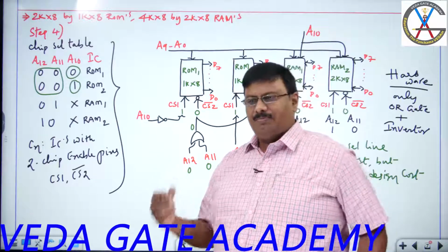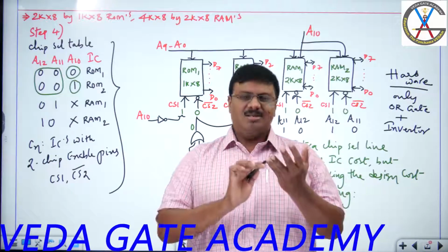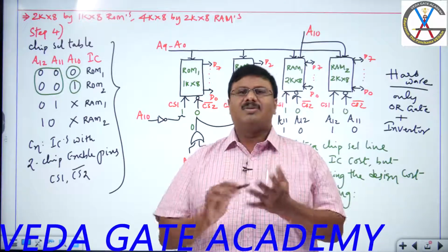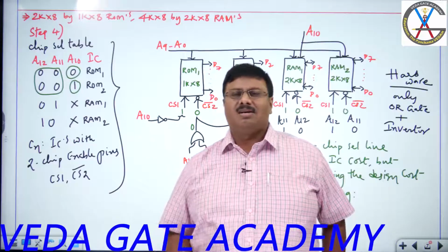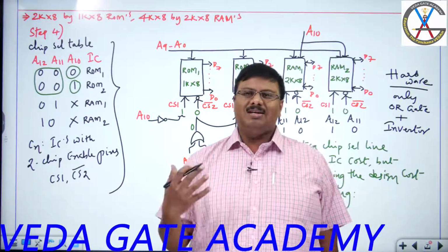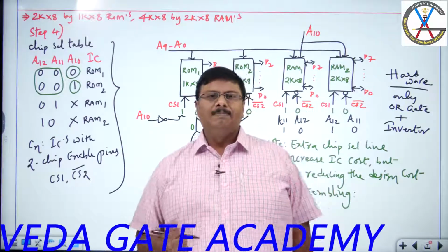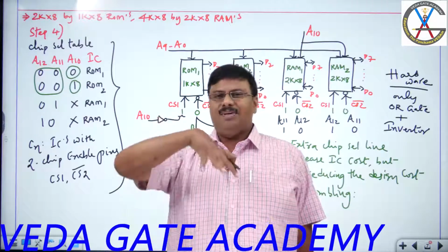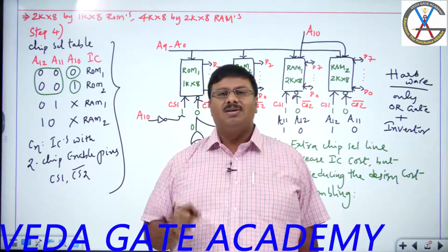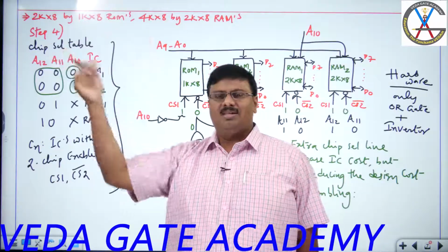So first, you frame the basic requirements: how many address lines for RAM, how many address lines for ROM, how many common lines, how many extra lines for other ICs, and how many address lines are to be taken as chip select lines. And always remember one thing: after allotting address lines to the ICs, the most significant part must be taken for chip selection.